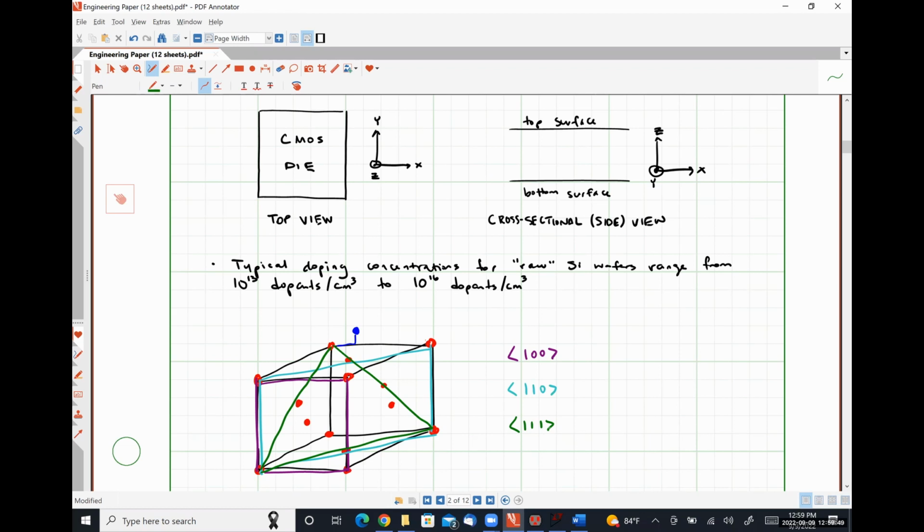The reason why the 100 plane is used in CMOS electronic fabrication is because it effectively yields vertical sidewalls when we etch or implant things into it, so that we don't have weird pyramidal shapes all throughout everything where we have structural gradients. We instead have nice rectangular wells when we start, and then when we heat the crystal up and things tend to diffuse, the corners get a little bit rounded, but it still plays nicely with everything that we're trying to do.